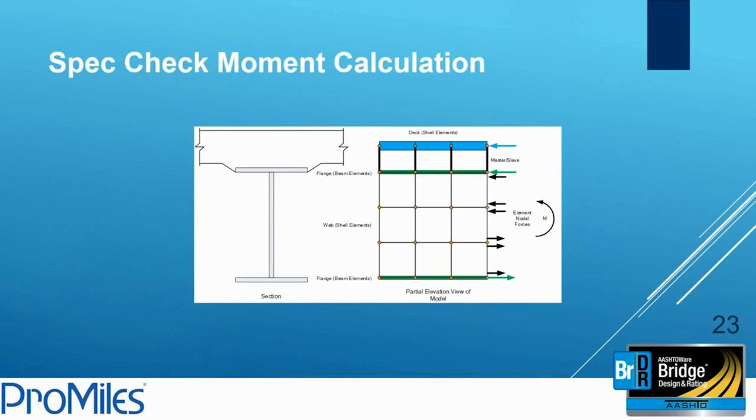I would like to mention just another point here. For dead load analysis, a direct transformation happens from a 2D moment to a 3D moment to a 2D moment. But for a live load analysis, we generate the influence surface by applying unit loads on the deck, and we generate an influence surface for each node on the girder, and we figure out the worst case scenario for certain actions, and then from that worst case scenario, we generate the 2D moment for that section.